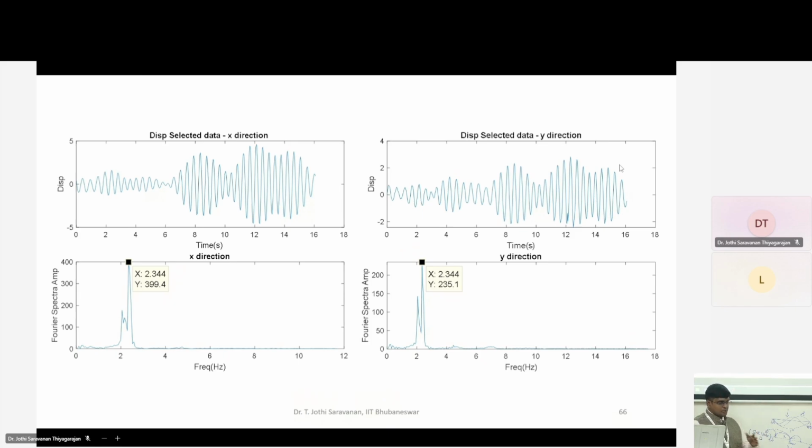There was one experiment where we were standing on a bridge and doing an experiment on a different structure nearby. Whenever a big vehicle passed, we could feel it. So we installed a small accelerometer on the tripod, to see wherever there is a difference in that accelerometer data. We look into that exact time step to see what is happening to the recorded data. That is one possible way, but it is better to avoid those locations. I suggest keeping somewhere where there is no disturbance, so that you will have a good recording.